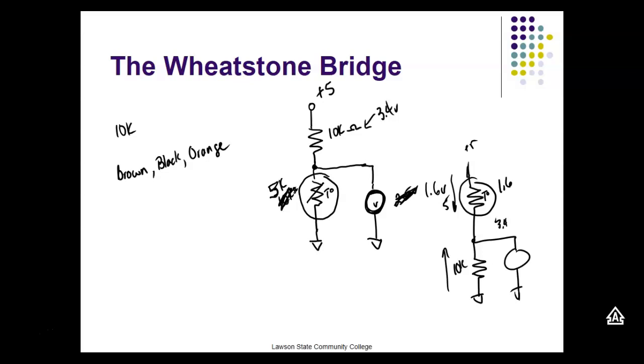So now we can come up here and get a voltage with a change in resistance, right? You understand that? So just about any sensor that changes its resistance with what it measures, we're either going to convert it into a voltage or into a current. Current's real easy, because if I wanted a current, then my current source would be down here, and my sensor would be right there. And the sensor itself, just putting it across a current source, would actually generate either which way we want to send it.